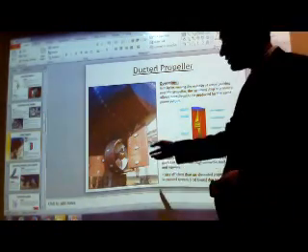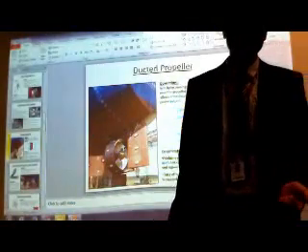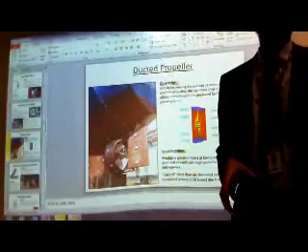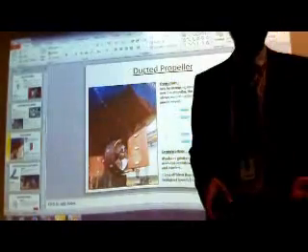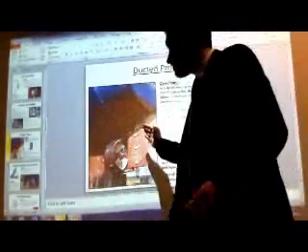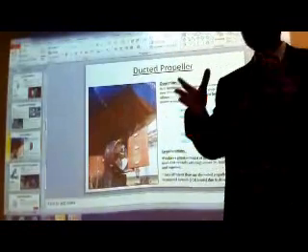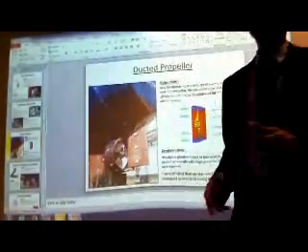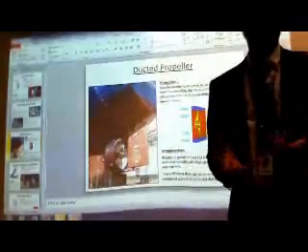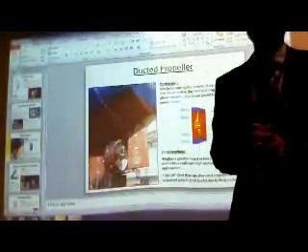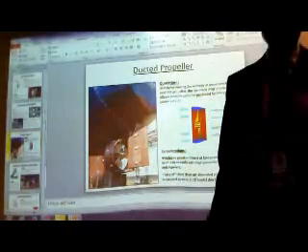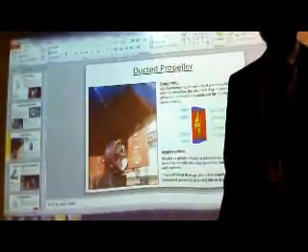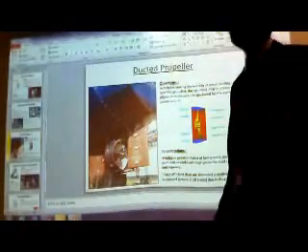When will you use the rudder? You can use the rudder when you want to maximize your efficiency. When will you change the flow of direction? Out there at open sea? No. Out there in open sea, you will keep this steady and you will play with the rudder to keep your vessel steady. But when you are at slower speed, you can use this to achieve maneuvering, and you might not need a tug or any other external propulsion system, or you can say an outsourced propulsion system. It increases your maneuverability.